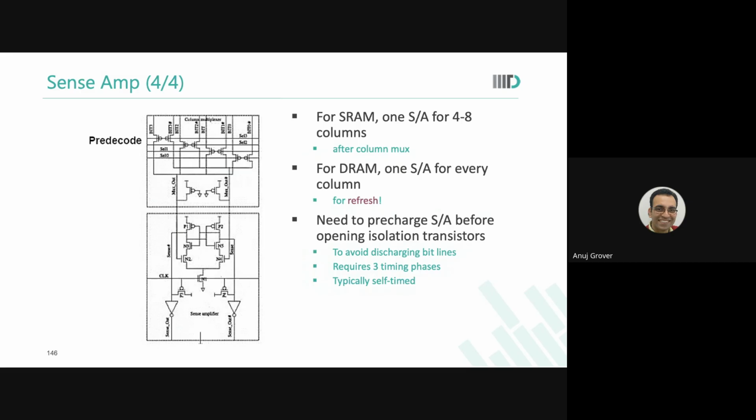So just jot this down: when we cover DRAMs, we should look at the sense amplifier aspect in a little more detail there. But over there again, you will see a latch-type sense amplifier is used, and it helps us do the refresh as we read. So we'll look into it again in some detail when we touch the DRAM sense amplifiers.